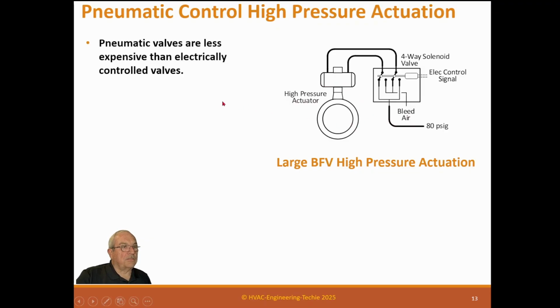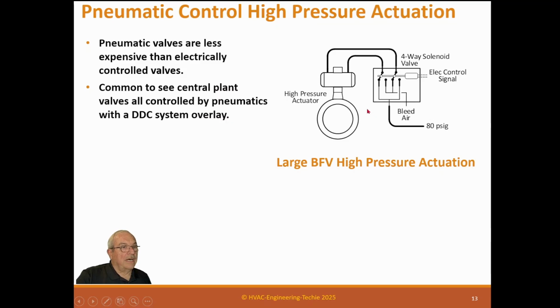Pneumatic valves are less expensive than electric control valves. It's common to see central plant valves all controlled by pneumatic with a DDC system overlay.